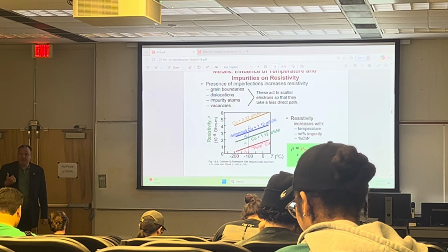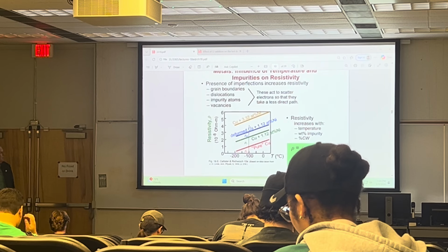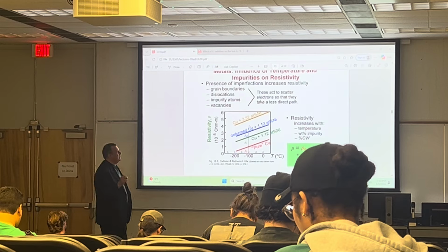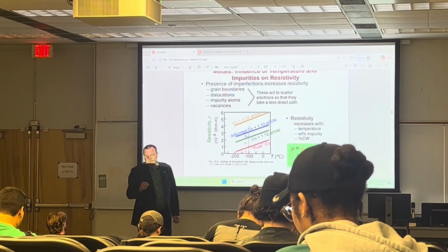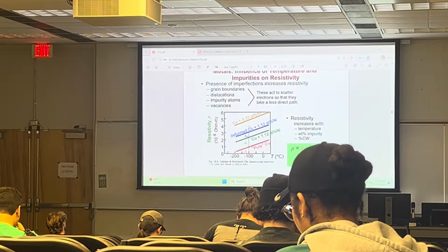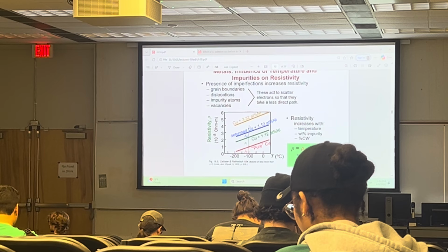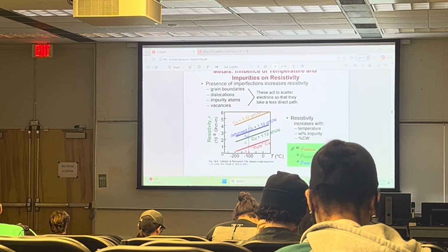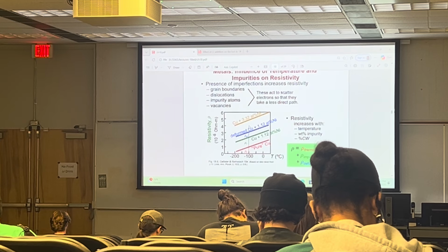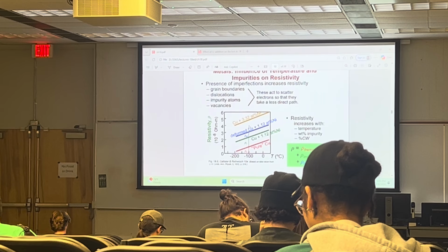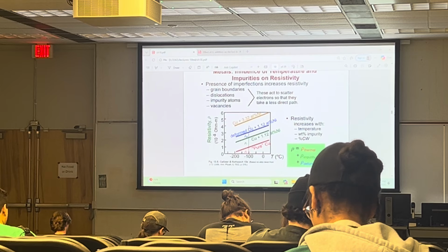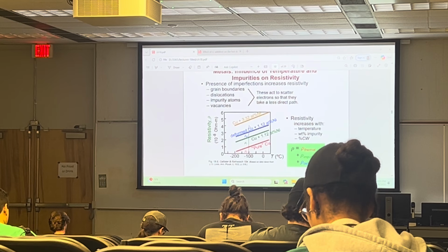And in the material, we have grain boundaries, we have dislocations, we have impurity atoms, we have vacancies. They all scatter electrons. They are preventing the free path which I'm taking now. But here, you know, I wish I could, but it becomes harder. You see that? I could, but it's harder. So this transport of electrons is hindered by all those grain boundaries, dislocations, impurity atoms.